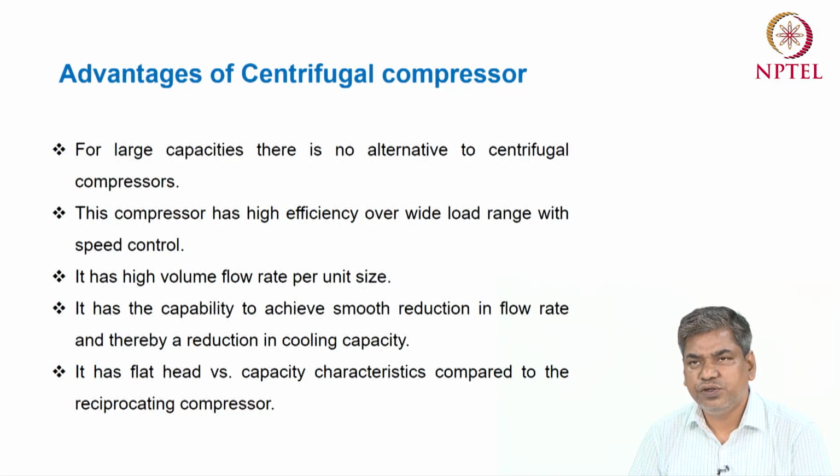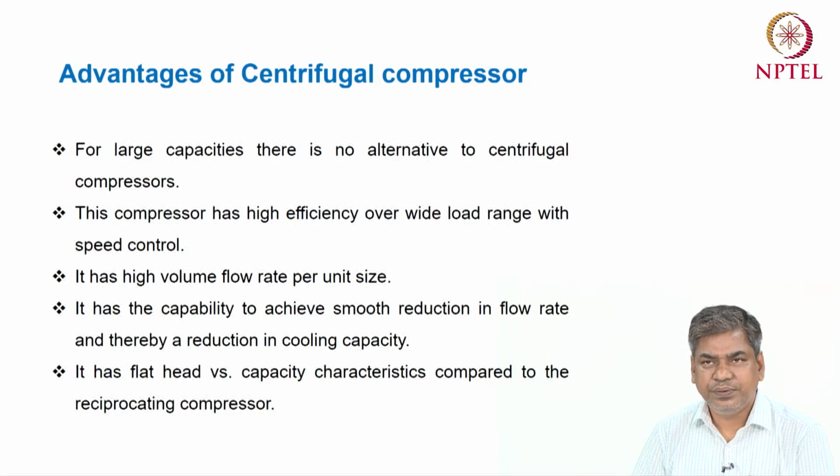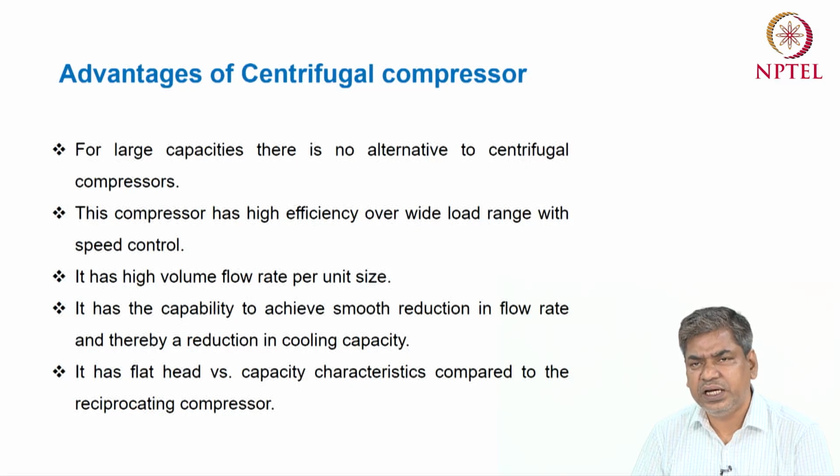cooling capacity. So for any case, if the cooling load is changing, then for that case we have to change the mass flow rate. So for this case, the change of mass flow rate, that process is very smooth as compared to the other types of compressor, and this has a very flat head or pressure ratio and capacity characteristics as compared to the reciprocating compressor.